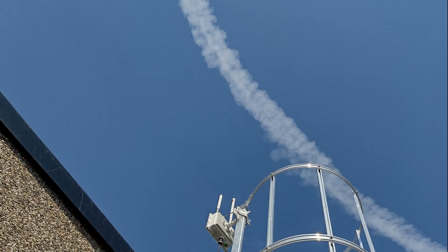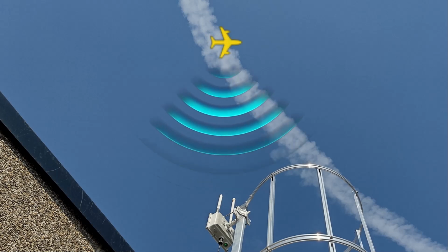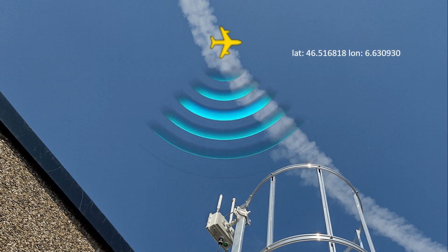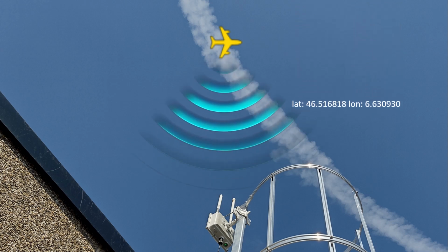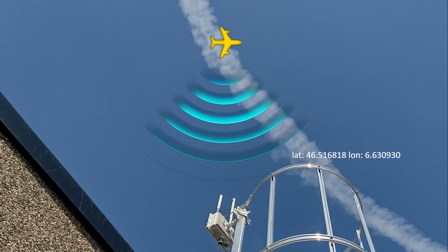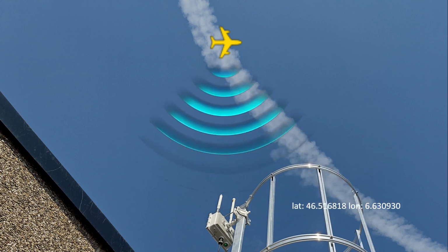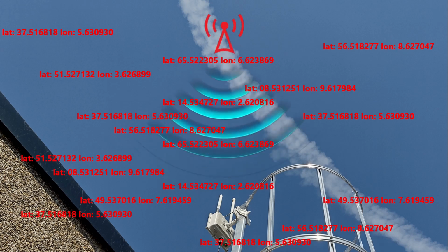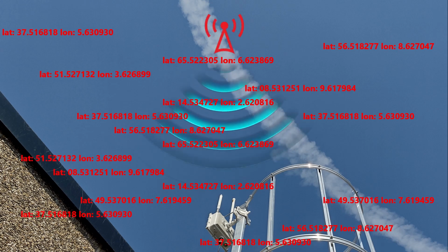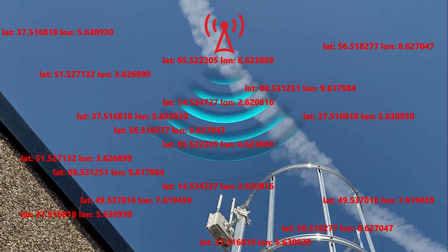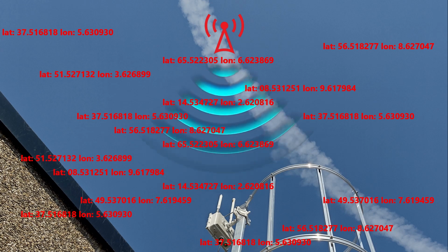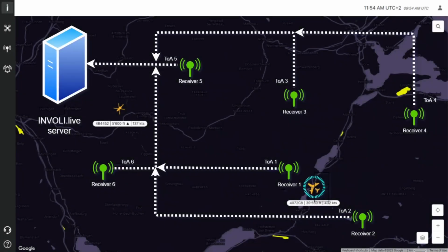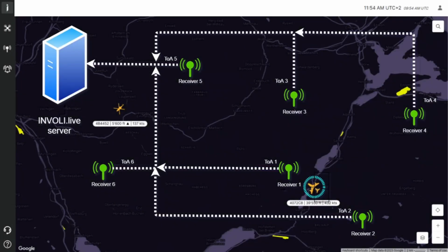Aircraft equipped with an ADS-B system readily provide information about their position, which is taken from the onboard GNSS instrument. Usually, the ADS-B position sent during normal operation and under usual conditions is trustworthy. But in some cases, it can be spoofed or erroneous, and to detect this, multilateration can be useful. In this case, we talk about ADS-B position validation. Let's now see the theoretical foundations of multilateration.